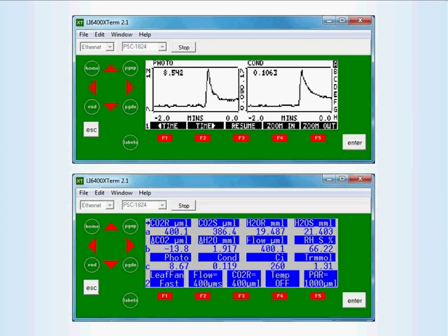After about 20 minutes, the reference and the sample gas analyzers were matched to eliminate errors due to analyzer offsets. The discontinuities that you can see in this strip chart on the top are when the gas analyzer was matched.